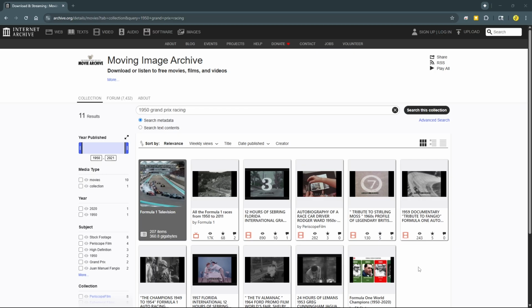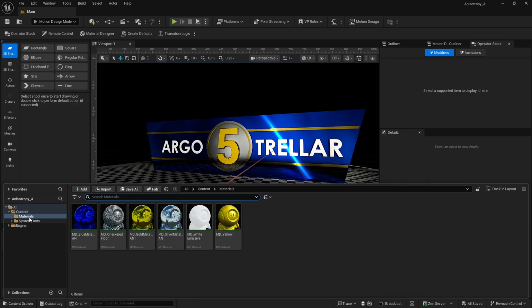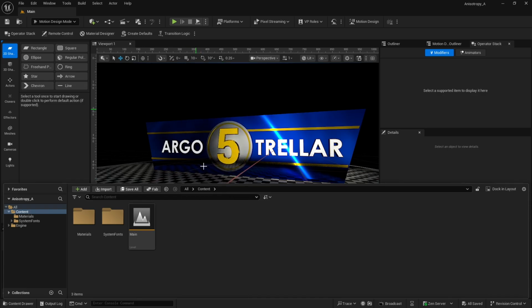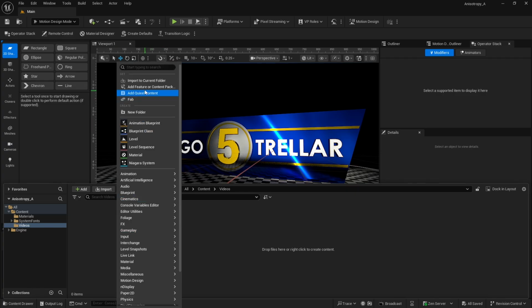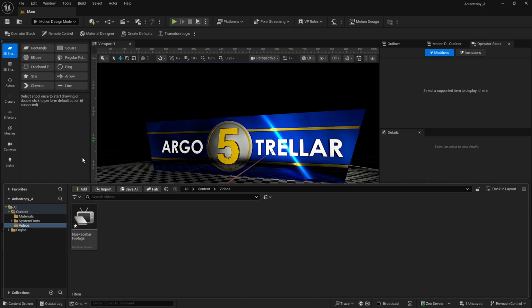took it into my editor, edited a few clips together, and exported that out as an H.264 .mp4, and that will work well in Unreal Engine. To import that footage in, I'm going to go down here to the content drawer, open it up, select contents, and add a new folder in. Label this videos, open that up, and right in there, we'll right click and go up to import and navigate to it. And there's the footage I want.